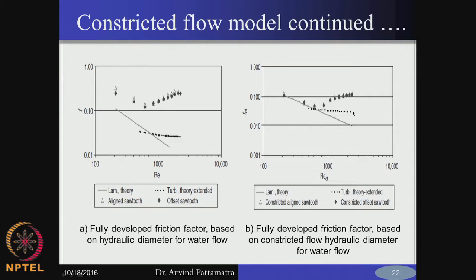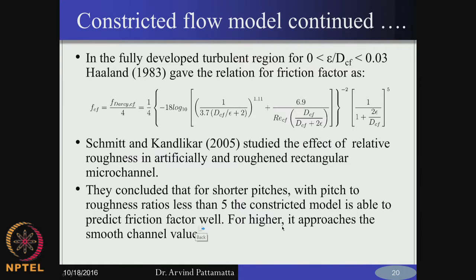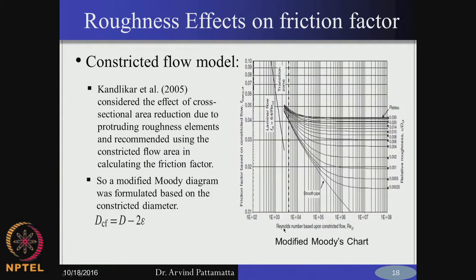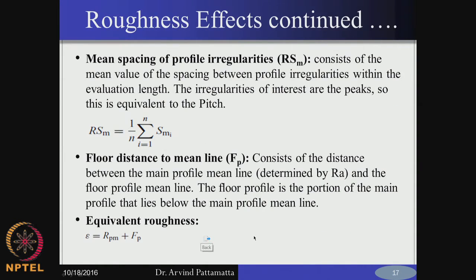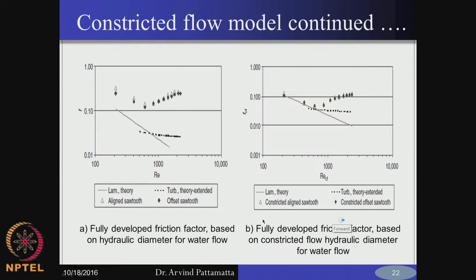Yeah. So, how big is the correction factor with respect to the diameter typically? Correction factor in the sense? So, the epsilon. This epsilon is usually of the order of few microns, because this is the roughness height itself. But the difference is very large because it is in log scale, right? You mean here? Yes, sir. The axis is in log scale, so it's like several multiples. Yeah, this is in the log scale, you are right.